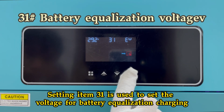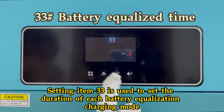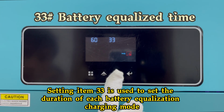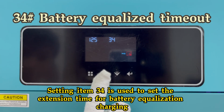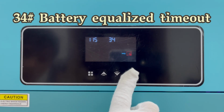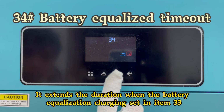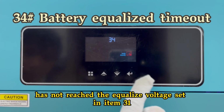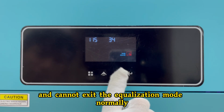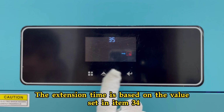Setting item 31 is used to set the voltage for battery equalization charging. Setting item 33 is used to set the duration of each battery equalization charging mode. Setting item 34 is used to set the extension time for battery equalization charging. It extends the duration when the battery equalization charging set in item 33 has not reached the equalized voltage set in item 31 and cannot exit the equalization mode normally. The extension time is based on the value set in item 34.